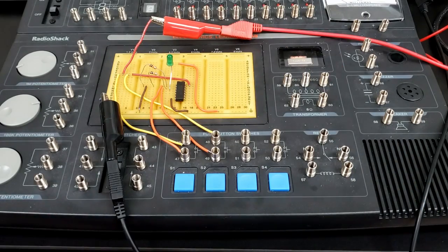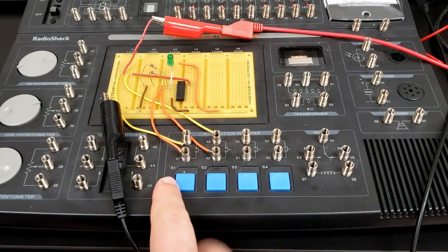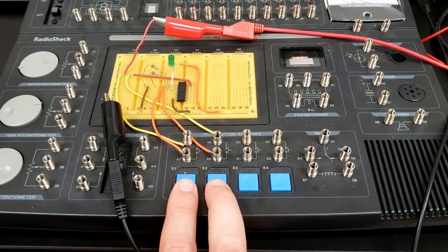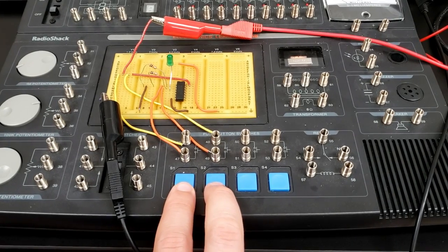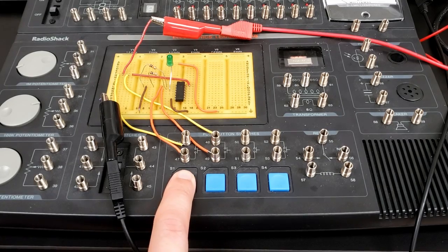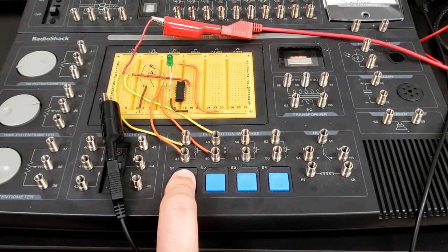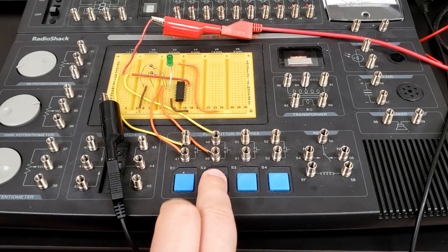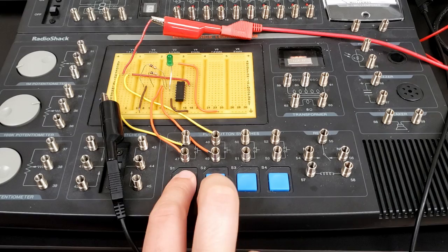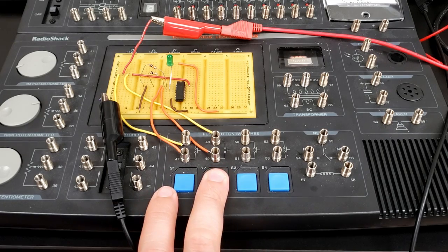Okay, so let's do this final one. This is again the 4070. So both of our switches are set to 0 now. So for input 0, 0, we have an output of 0. For input of 1, 0, you can see that the light is lighting up there. So that means that we have some output. If I hit 0, 1 now, again, we have some output. So for 1, 0 and for 0, 1, we have an output of 1.